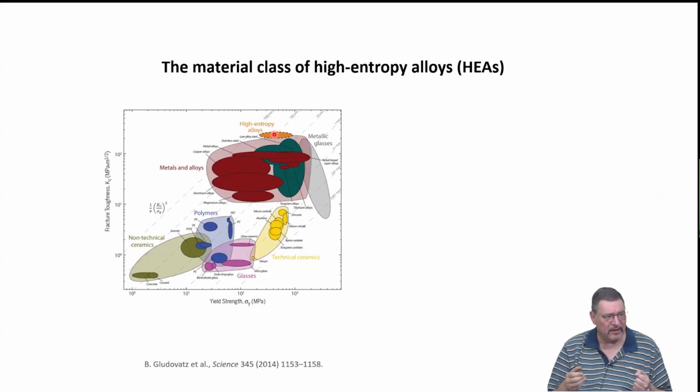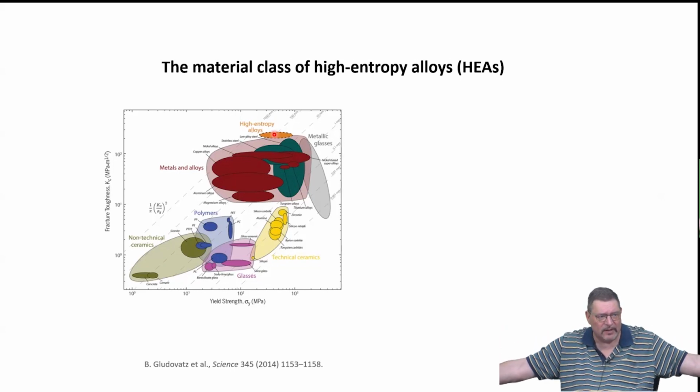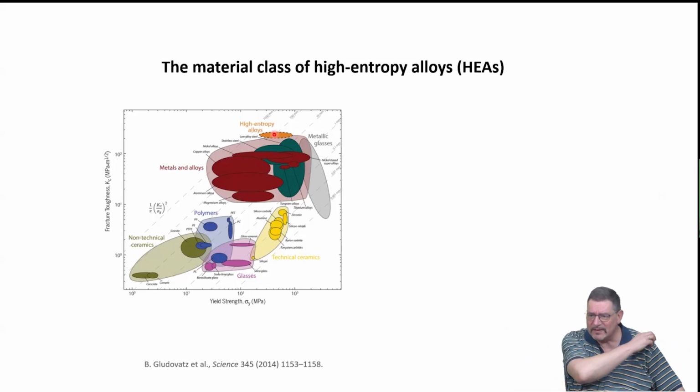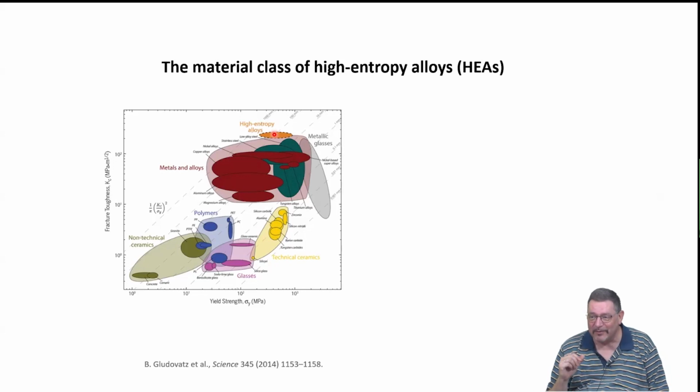Right? So if you sit in an airplane, you often see the wings flex like this if you have a little bit of turbulent weather. Actually, there are many, many cracks where the wing is connected to the airplane, but they are all subcritical. So the Kc value is high enough to prevent these subcritical cracks from becoming supercritical. If it's supercritical, you don't want to be in the plane, because then the wing falls off very shortly, right? So this is really a very, very important quantity.